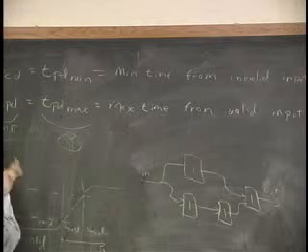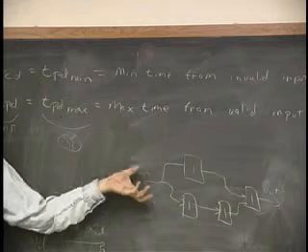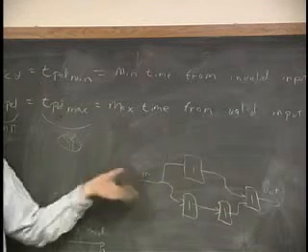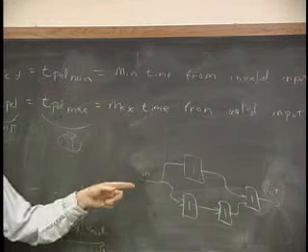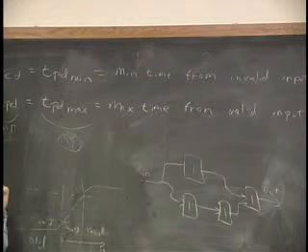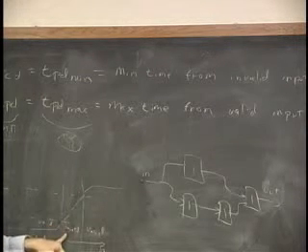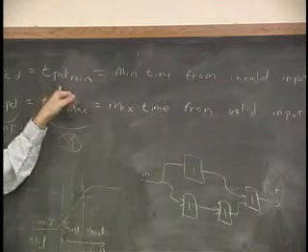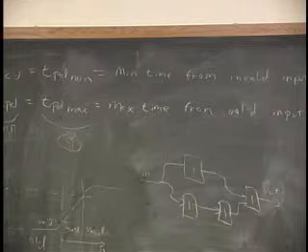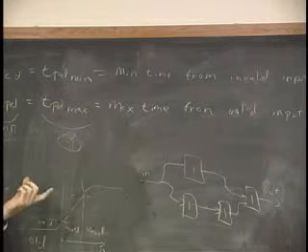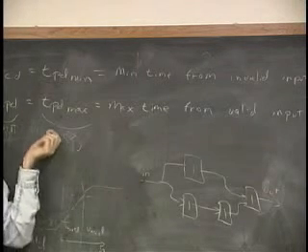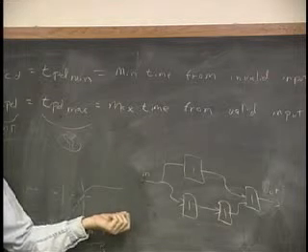But it turns out that in designing circuits that do timing on the data that flows through here, when we're worried about how fast data goes through, the TPD min, we actually are concerned about how fast invalid data goes through. So that's why, in general, TPD min is a measure of the invalid input to invalid output time. Whereas when we're worried about how long it can take at most for the data to go through, we care about how long it takes the valid data to go through.